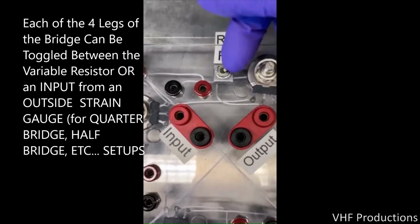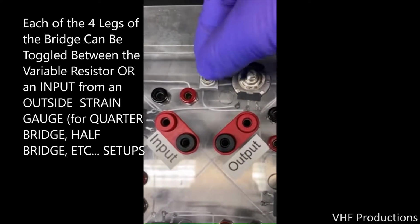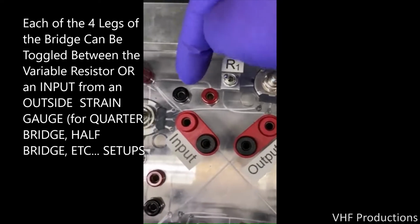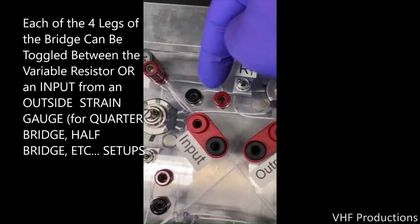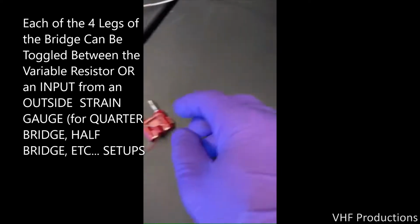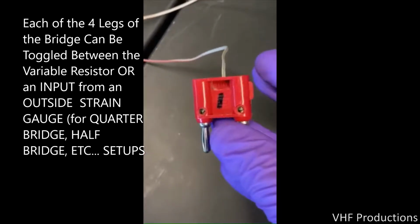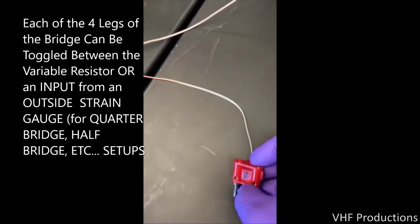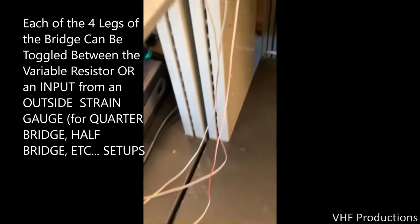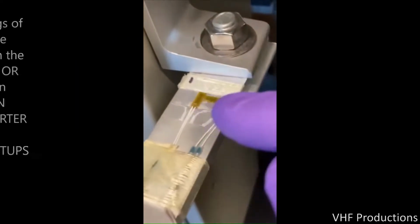Before beginning to utilize strain gauges, we need to set up the Wheatstone Bridge to match the resistance of the strain gauges themselves. Throughout this lab module, we will be using strain gauges with an initial resistance of 350 ohms. Therefore, before using the Wheatstone Bridge, we need to establish that all four sides of the Wheatstone Bridge have a resistance of 350 ohms. In other words, we need to make the Wheatstone Bridge balanced.